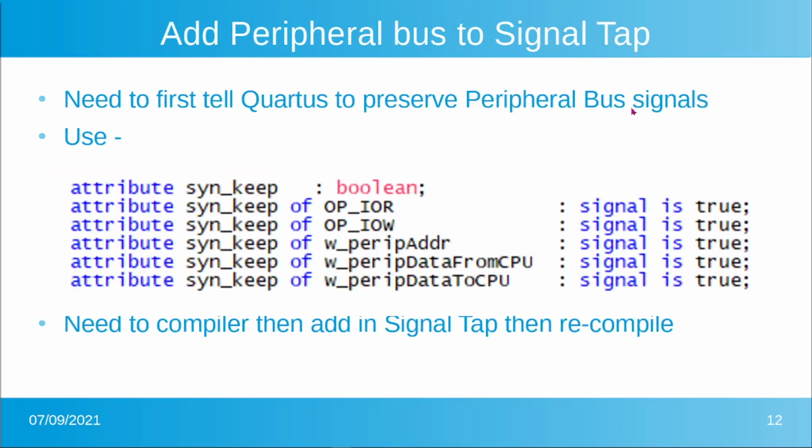All right, so far we've just played with a switch and a light, but things are getting more complicated, and I think at this point it would be useful to hook up the peripheral bus signals to a tool called Signal Tap. This video is going to be a little bit longer because of introducing Signal Tap, but imagine you have a very expensive logic analyzer sitting on your bench next to this card, and you wired everything up, and you want to see what the values of those signals are.